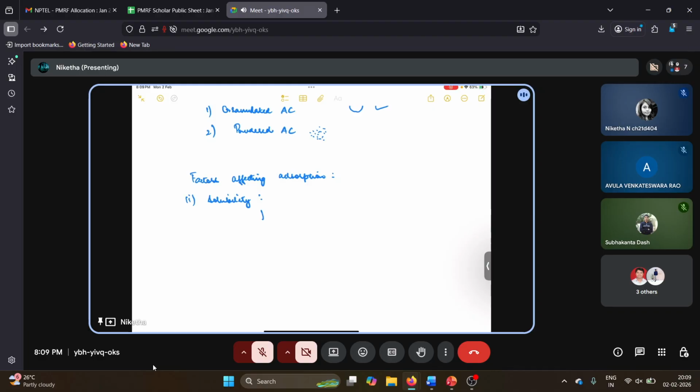But if a substance is less soluble, then it can be adsorbed easily. For example, if we have a mixture of water and oil, absorbing the oil or grease is very easy compared to absorbing some dissolved organic, because it is not attached to water, so it will easily stick to the surface of the adsorbent. That is why highly soluble substances are more difficult to adsorb.